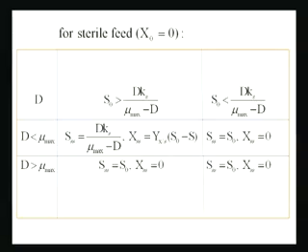Yeah. So, this stability criteria that you obtained over here is for all possible values of mu. So, some of the things that you might want to do is look at how you change your mu, and how it changes the stability of the system. Now, it may be a little boring to do that to start with, because of the maths, but once you go through the maths and you essentially will come out, one of the things you might want to tell me is whether our intuition that for all del mu del s less than 0 the system is unstable. That's a question I pose to you.